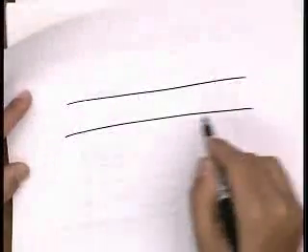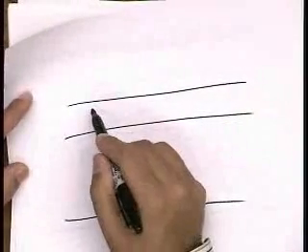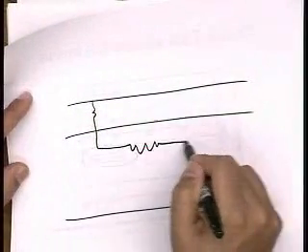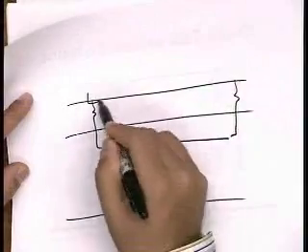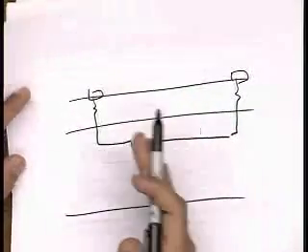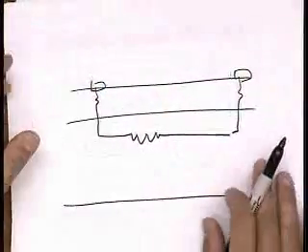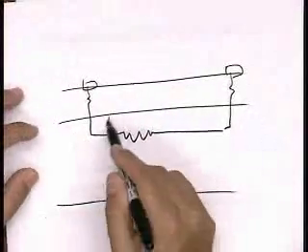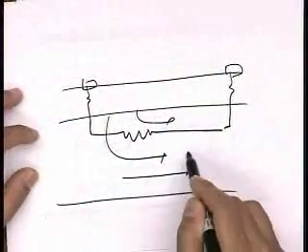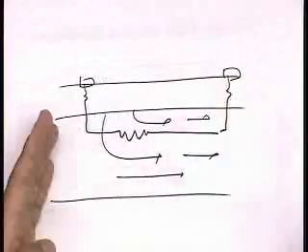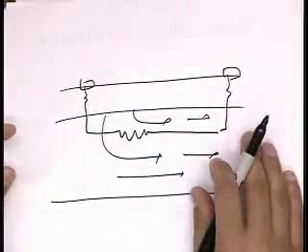And again, with this model, it makes sense, because for a lightly doped substrate, this resistance is a major part of the total resistance. So as I increase the distance between these, increasingly the substrate material just looks like a resistor where current is flowing in this direction, and changing this length changes that resistance.